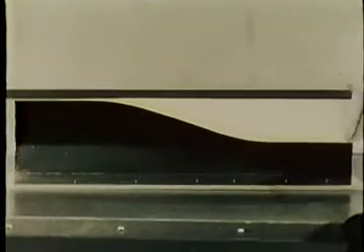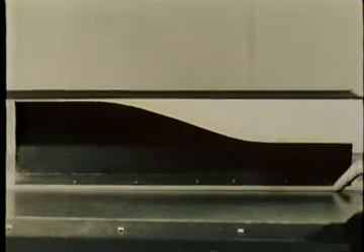First, the case of a decreasing pressure or favorable pressure gradient in the flow direction. We will use this 2-to-1 flow contraction and watch the boundary layer along the flat side. The upstream boundary layer is growing slowly as it enters the contraction. After the contraction, the boundary layer is thinner. Note that the distance from the wall to the streamline downstream is about half what it is upstream, because the two-dimensional flow contracts 2-to-1.